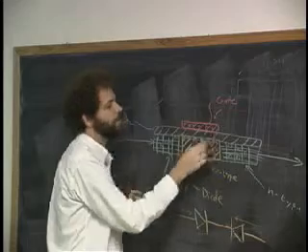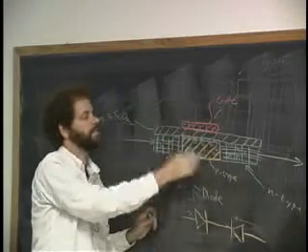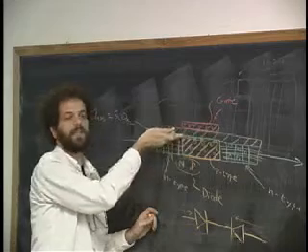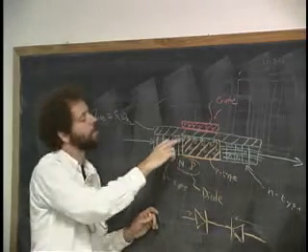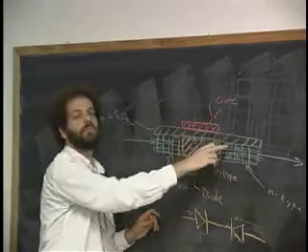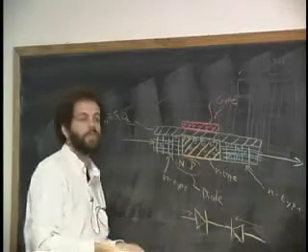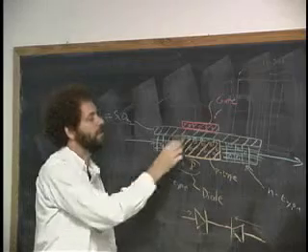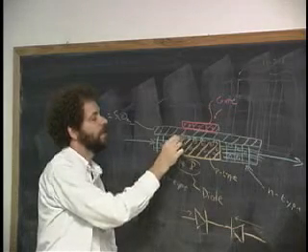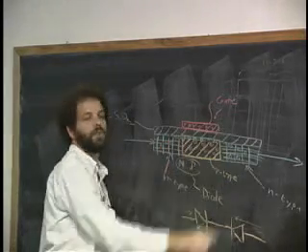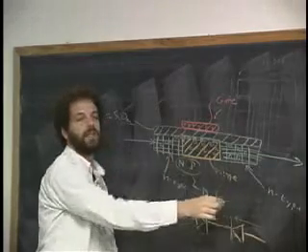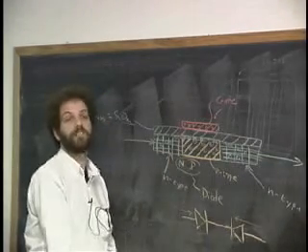And this material, which was originally p-type throughout, because you put positive charge up here, gets a thin layer on the top, sort of like water on ice, where it actually switches to be n-type, because so many of the negative charges have been attracted to the surface. And look what just happened. Suddenly, I have a clear path across this NPN junction. That's all n-type, and n-type works just fine. And it's a closed switch.